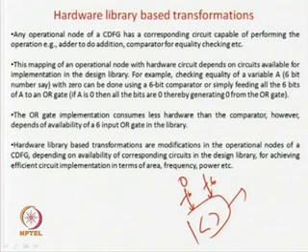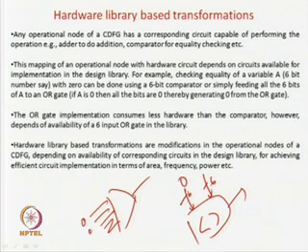Another very simple way of doing it is this: you connect all 6 bits of your bus to a NOR gate. If everything is 0, then you get the answer as 1, and so forth. So, very easily you can say that a 6-bit NOR gate is a comparator for 0 of a number. If all bits of a number are 0, then the number is 0. So, if you feed all the bits of an n-bit number to an n-bit NOR gate, and the output is 1, then you know that the number is 0, else it is not.